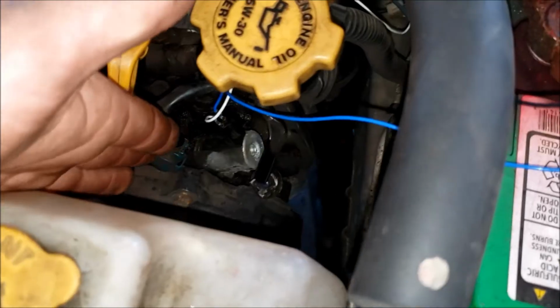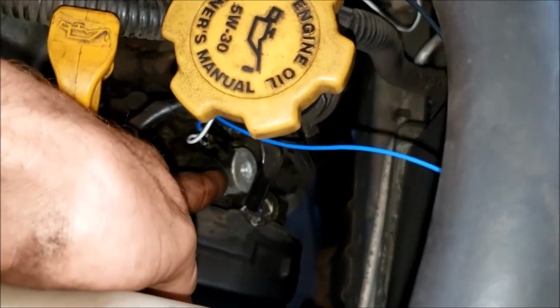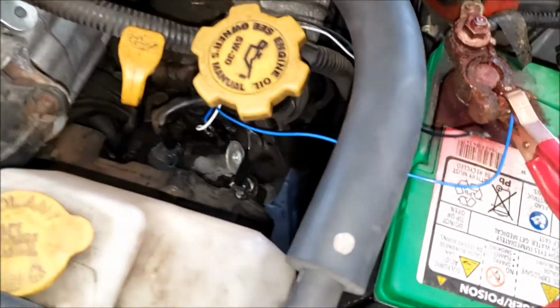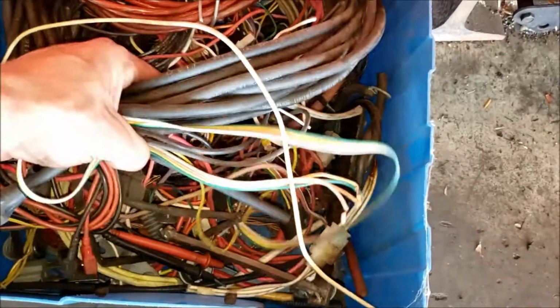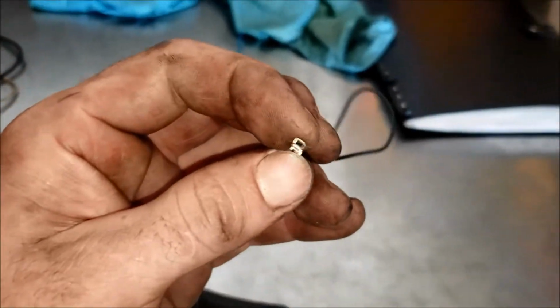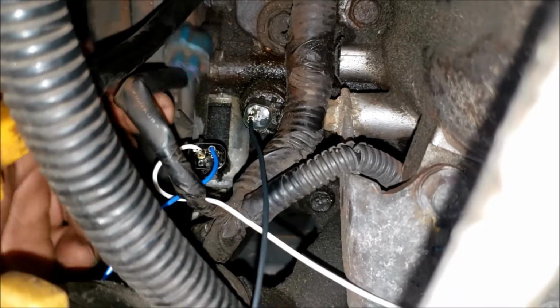Jumping back over to the passenger side, I already have my connections off, and we now want to energize this solenoid and see if it clicks or changes the engine RPM. So you can use alligator clips, or you could use a power probe like this, or probably the best way is reaching into your junk drawer and getting some old wire leads. I have this old oxygen sensor lead, and I pulled the terminals out, and then you could take those and slide them right onto the terminal pins, nice and clean.